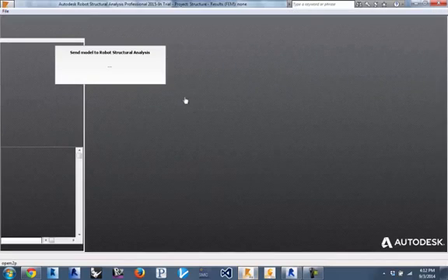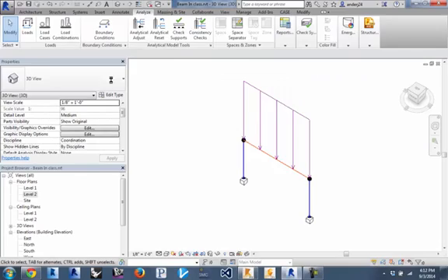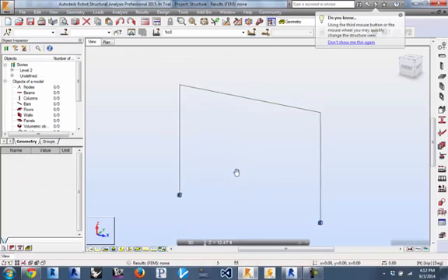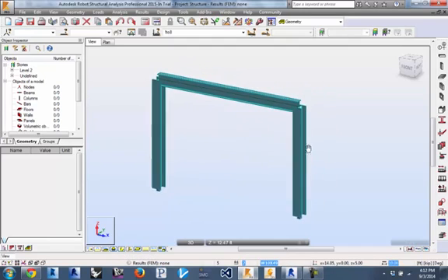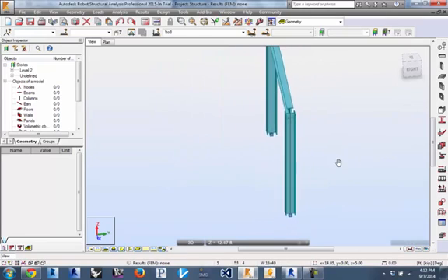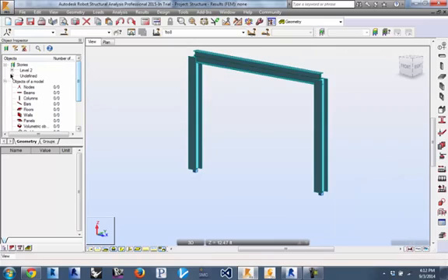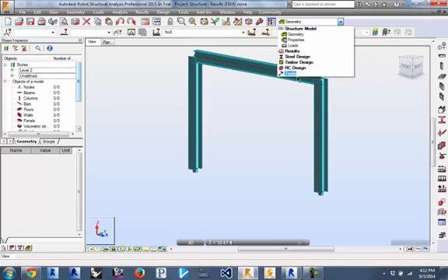Normally when we push this over to Robot, it usually opens up, and then in here we get the sections that come through. Up in the top right, we have an understanding of what the levels are. Each level knows what beams and columns are on it, and has all those sections. A lot of the navigating in structure is done here. We can understand this from a geometric standpoint: properties, loads. We'll be doing a little bit of the steel design at this point.